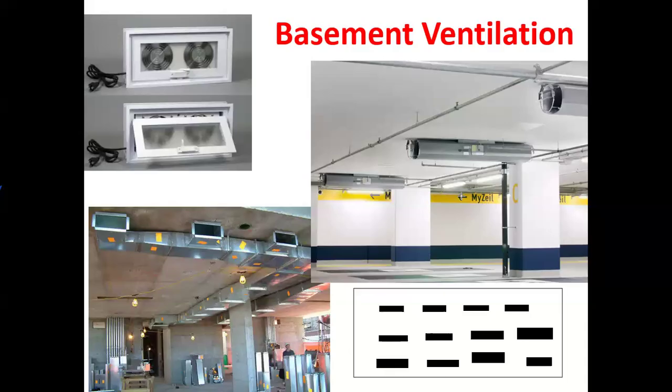Normally, if you consider a commercial area, we can avoid the duct costing by implementing this kind of jet fans. Normally, guys, here we don't need to operate these fans at full load. Why? Because an area probably has peak hours and non-peak hours. For example, a commercial building, that means a shopping complex. In the evening, the number of persons is comparatively high at that time, isn't it?